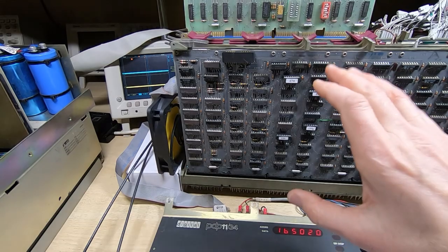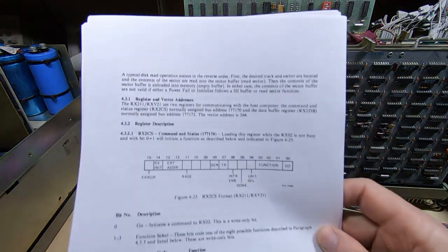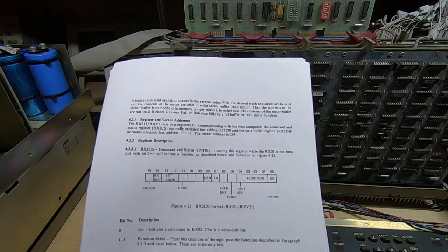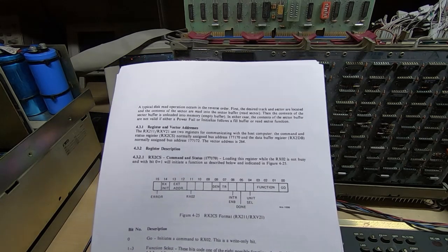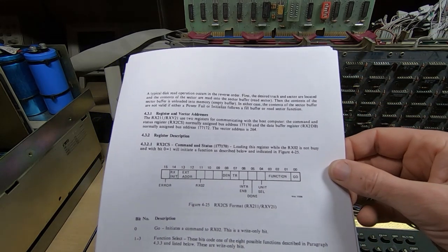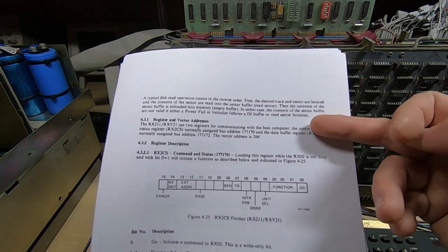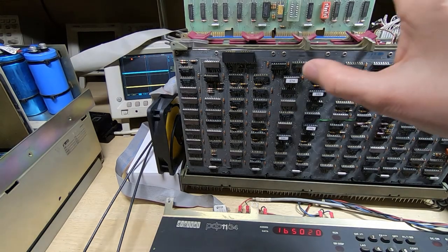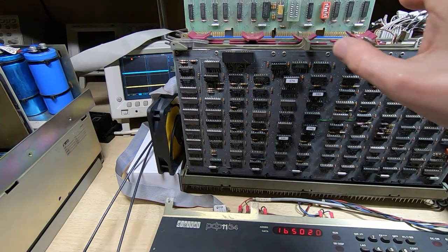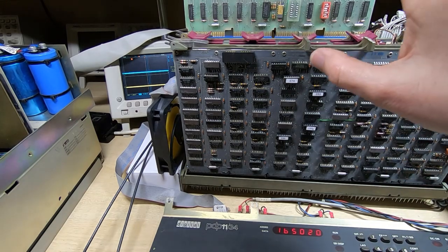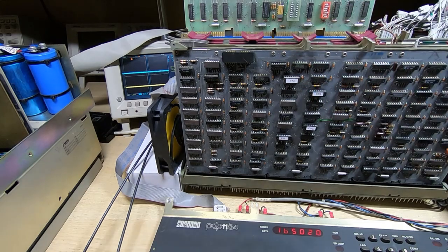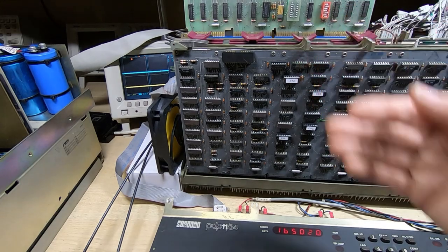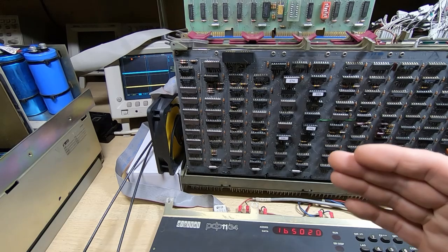Now luckily there's a lot of documentation available for the PDP11, and part of that is the documentation for driving the RX02. It's quite complex, it gets quite involved, but if we break it down into sections it becomes much easier to deal with. So the first thing to bear in mind, and I don't really like working on these RX211 boards, is that they're very tricky to work on. They're actually a state machine, and it's all hard coded, so it's very difficult to fault find on, because what you're looking at any instant depends on the sequence of events prior to that.